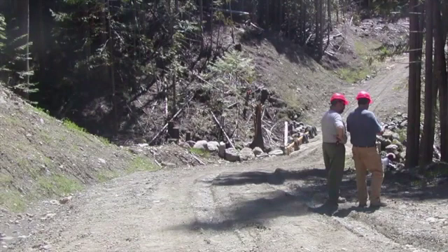For all the components in our site, the road surface and the cut banks, we need to make an assessment to determine how much sediment is coming off each of these areas and how connected they are to the stream. In this case, they are all directly connected to the stream. They have a connectivity of 1. We can come up with a simple estimate of how much fines from this road will get into the creek over the coming year.